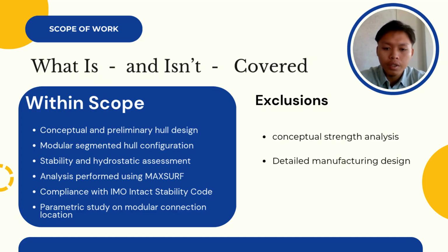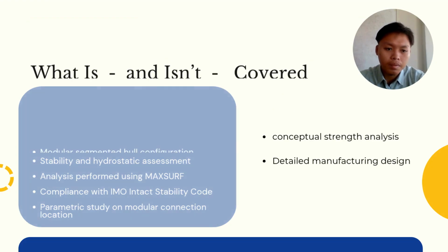This project will evaluate hydrostatic properties such as displacement, buoyancy, center of buoyancy, and metacentric height. The vessel's stability performance will also be assessed under different loading conditions and compared with the IMO intact stability code requirements. Additionally, a parametric study will be conducted to investigate how different modular connection locations affect the vessel's performance. However, structural and strength analysis, material selection, and detailed manufacturing process are beyond the scope of this research.